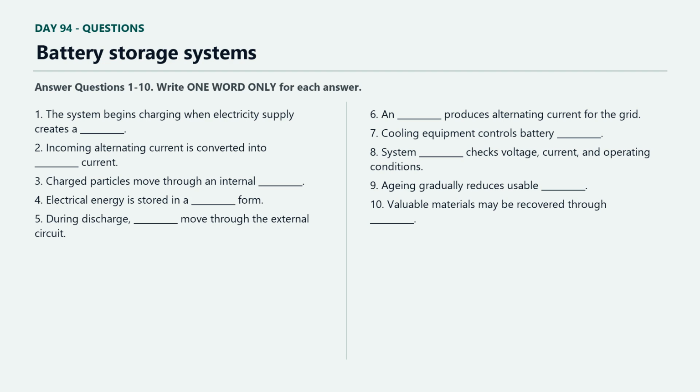Grid equipment and most connected loads require alternating current. An inverter converts the direct output into alternating current with the required frequency and waveform. Modern units can respond within fractions of a second and may also support voltage or frequency control. A transformer then matches the output voltage to the connection point. Protective switches isolate the plant if measurements indicate a dangerous fault.